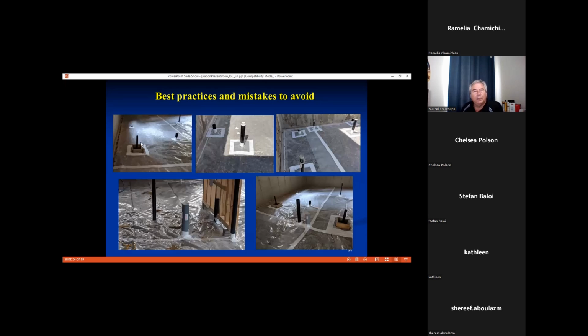So you can see here, this was a membrane that we installed. You can see that wherever the pipes came through, it's sealed. And wherever they overlapped, we made sure that we have a bead of acoustic caulking. We need to overlap by 12 inches. So we have a bead of caulking where it overlaps, and we put tape. Now the tape, a lot of times, is just to allow the caulking to dry. As we're walking around on it, we don't want to trip on the end of it, and we want to make sure that the sheets don't move on us and break the seal. So that's why we'll put tape also at that point.